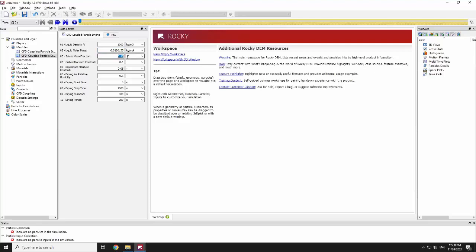The solute mass fraction input parameter is for when, for example, as I mentioned in the food industry, you have sugar in your mixture, and then when this mixture dries, only the solvent will be drying out, and the solute will actually remain and be included in the particle mass. But here, since we are just removing water from the particles, we can eliminate this one, okay?